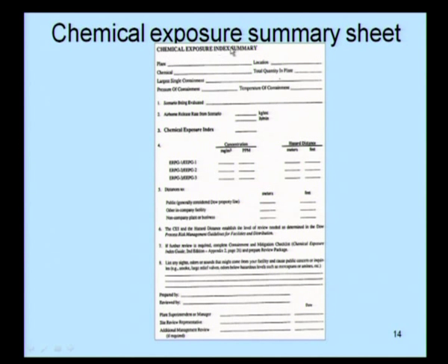So, all these are basically prior information available to you before you start the CEI. Now, you pick up the scenario being evaluated. Is a scenario a gaseous release or a liquid release? For that release, try to determine the airborne release rate, which is AQ, given in kg per second or pounds per minute. I will advise you to strongly follow SI units, therefore fill up the value in kg per second.